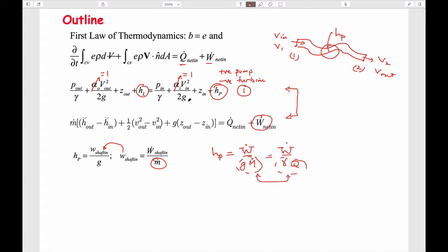So Bernoulli's equation with the head loss terms and the head pump terms. We'll talk a bit later about the head loss terms. And also Bernoulli's equation with the energy loss components, including enthalpy, again written between, I guess this would be H1 and this would be H2 in this parlance. This would be H2 and this would be H1. So always one-dimensional flows. The velocities are always positive. Doesn't really matter because you square them, so even if they're negative, they come out to be positive.